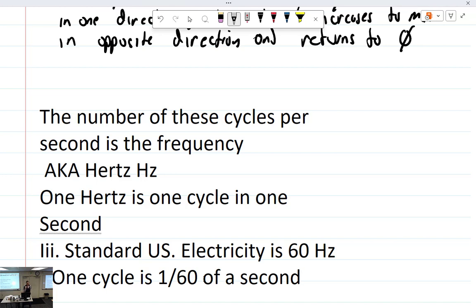If I was given the hertz, you have a key on your calculator that converts it to time, and that is the x minus 1 key. So 60 hertz, x minus 1, equals 0.0167. And if we took 60, x minus 1, times 60 equals 1. So that works out. So it's 1/60th. To convert one to the other, it's x minus 1.